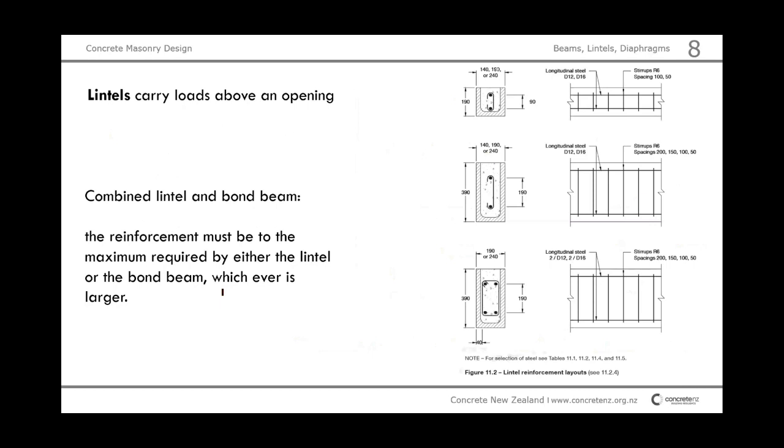So that was the diaphragm and the bond beams. Now lintels. And again, I will show you now on example of this simple house how we design a lintel for that simple house. There are ready-made options in tables in 4229. There are 190 millimeter tall lintels and 390 millimeter tall lintels. And there are tables for these.